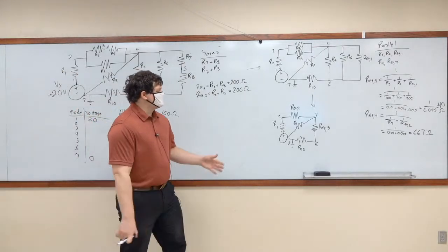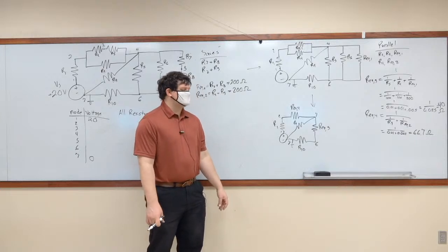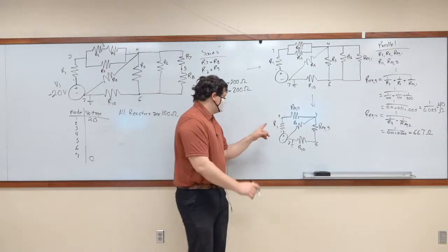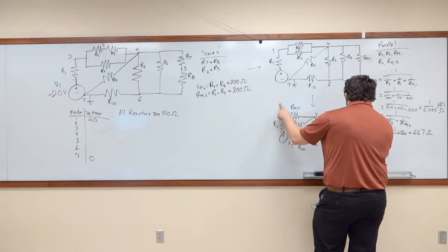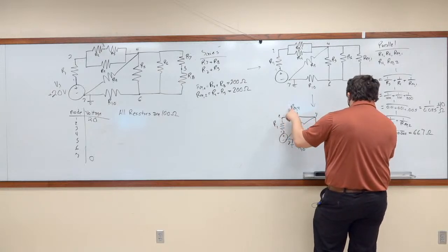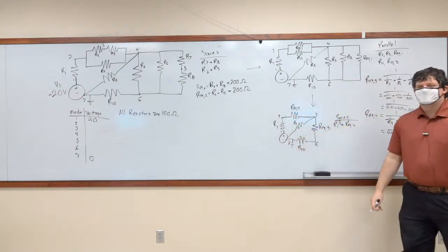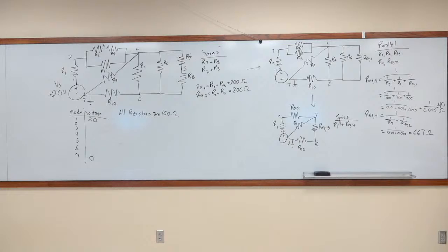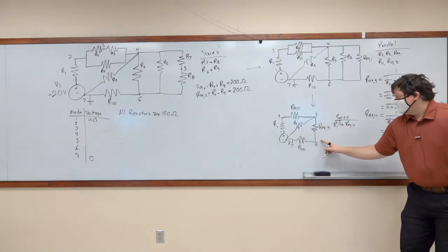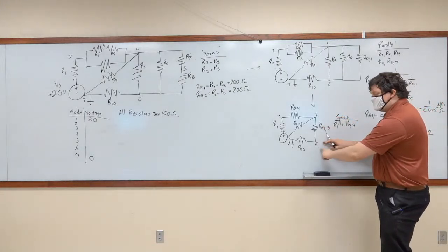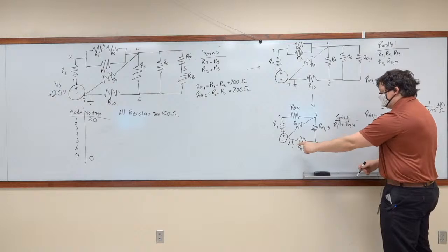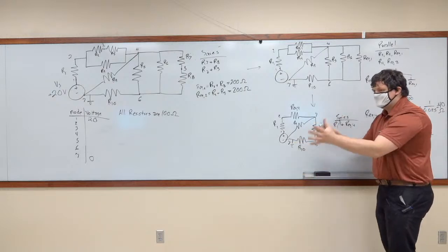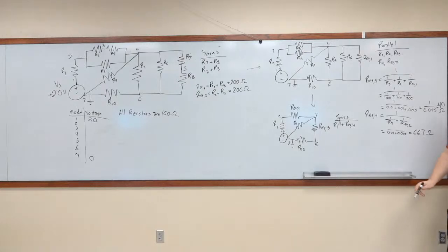Do we have any resistors in series here that we can combine nicely? R1 and R4, that one. So series R1 and REQ4. Do we have any other resistances in series that combine nicely? REQ3 and R10, right? Because they both share one output, that makes them in series. One single node with only 2 resistors connected to it. One resistor is input, one resistor is output. They're in series.